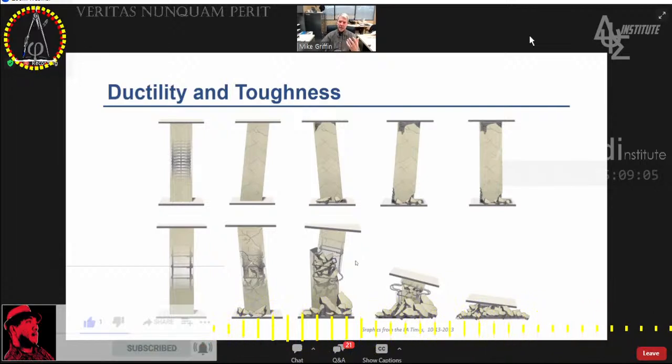So in our non-ductile condition, in concrete frame buildings, our concrete takes our vertical gravity forces, whereas our steel takes our lateral forces in the building. And so in our non-ductile condition, we're breaking up all of that concrete and causing it to just fall out. Well, we don't have any vertical support anymore. The steel cannot take the vertical loads that were there for the concrete to take. That's the difference between the two materials. And so that's why these become collapse hazards and are very important to either retrofit or get out of our built environment.